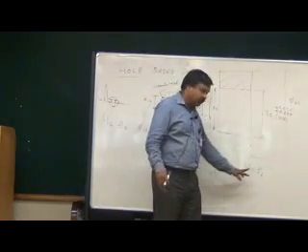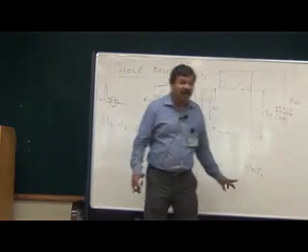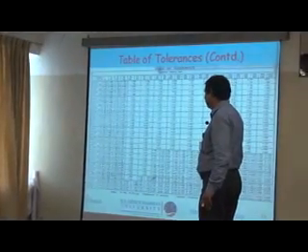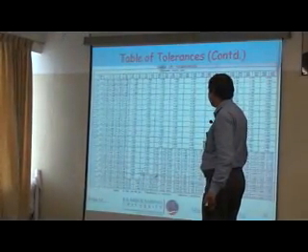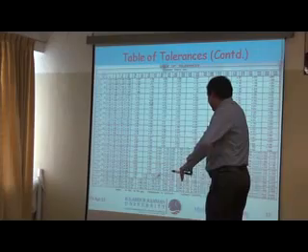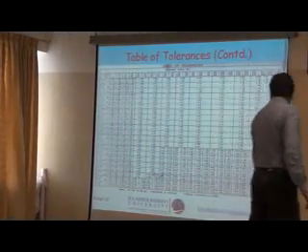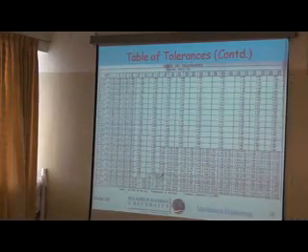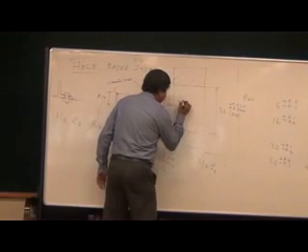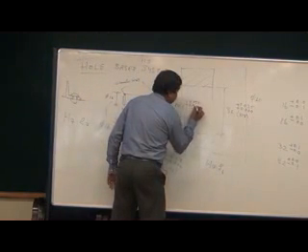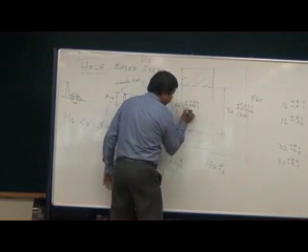Coming to the shaft, it is S6, small S6. That is S6, 32 mm diameter. It is plus 59, plus 43.